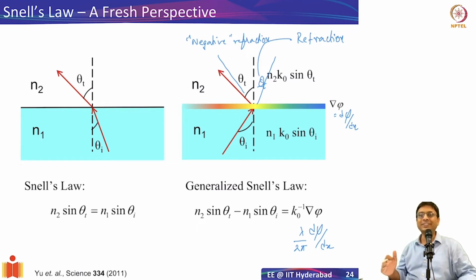So the question is, basically you can have any angle of refraction. Well, the problem physically will turn out to be how much gradient you can generate physically, and I'll talk about that in the next slide. The idea is we are trying to put antennas, right? If you have a certain size of antennas, there's only a finite number of them you can put. These are not infinitesimal antennas. These are not point dipoles. These have some physical extent. I'll show you some examples of the physical extent. Once you have two antennas, I can't merge them. I can't overlap them. So the spacing between the antennas is eventually what will determine my bending angle. That's the physical limit that comes in.